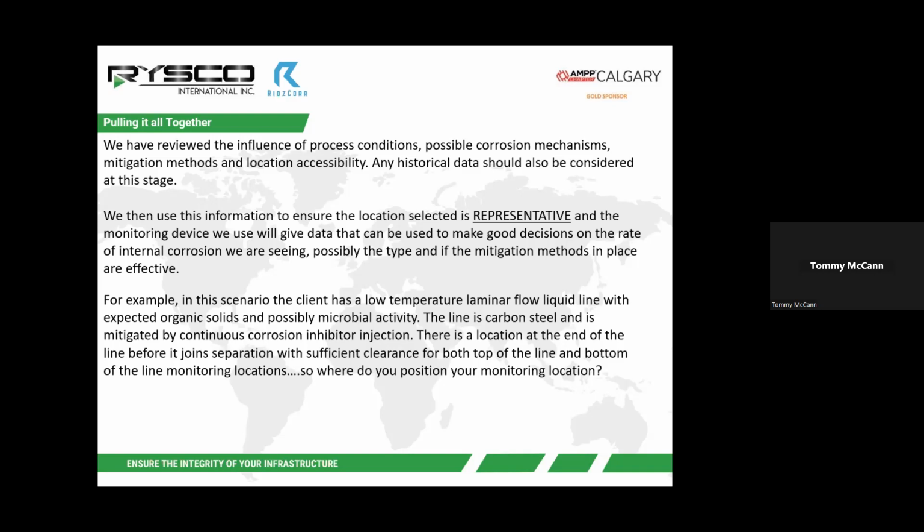That's also something that would come into the consideration. When we use this information, we talked about it before, we want to make sure the location selected is representative, and the device will give us data that we can use for effective decisions, and how we are measuring and mitigating that rate of internal corrosion, and possibly the type of mitigation methods, are they effective?